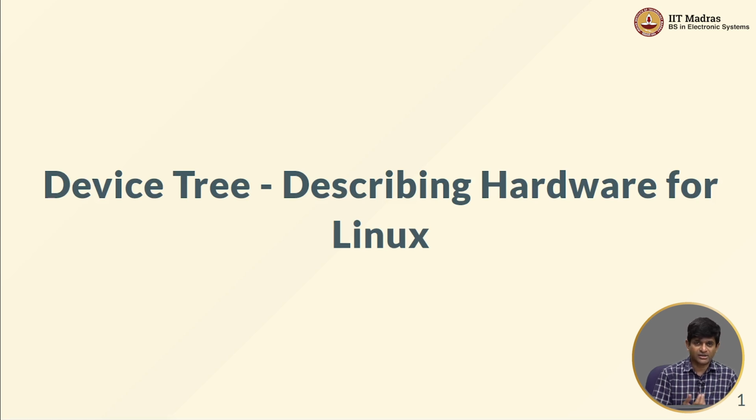But we are primarily interested in understanding how we can get embedded Linux, whatever that means, right, working together with a hardware software interface where we basically have some kind of an FPGA type of platform, right? And it turns out that the approach that has been used in embedded Linux, especially on ARM based devices as we have in our Xilinx FPGAs, is to use something called the device tree in order to describe the hardware.